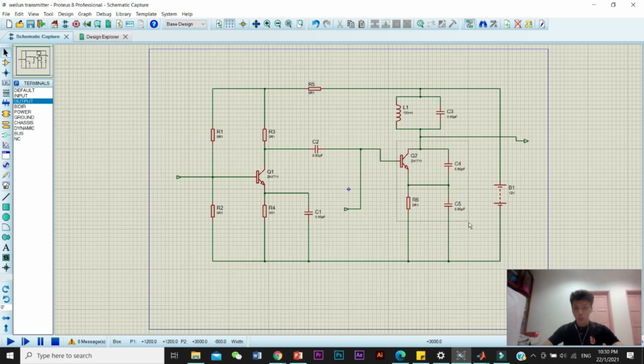This is the amplifier before the modulated signal is sent out. This is an emitter resistor. This resistor ensures the oscillation will not shunt to the ground. This is the ground of the circuit.